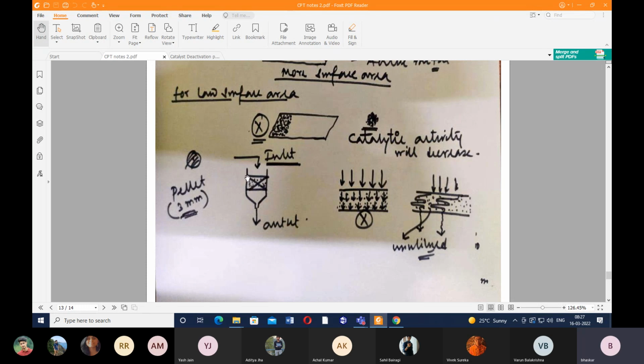So we have got a reactor, and inside this I have got a bed. Okay, in case of petroleum refinery, I'll teach you that we don't use a bed made up of powder. Instead of using a bed made up of powder, we'll use pellets inside this bed. That means we have got layers of pellets. Pellets will be made up of this catalyst only. So catalysts are basically in the powder form, right? So if the catalyst is in the powder form and we are incorporating those powders inside this bed, then what would be the scenario? Can anybody tell me?